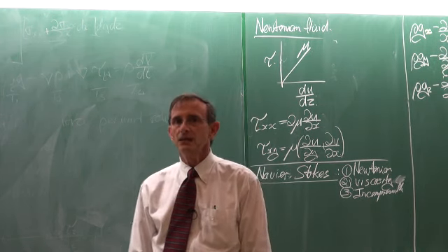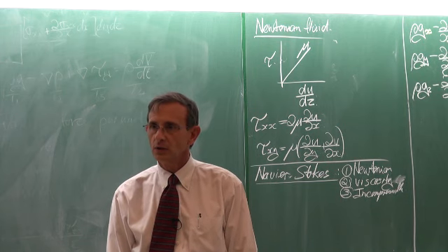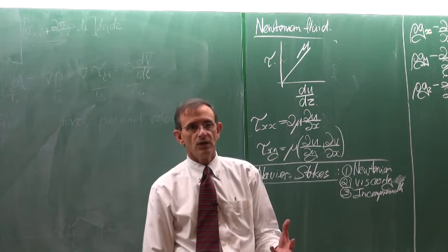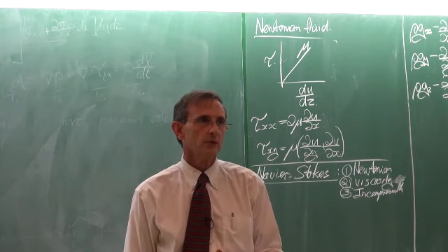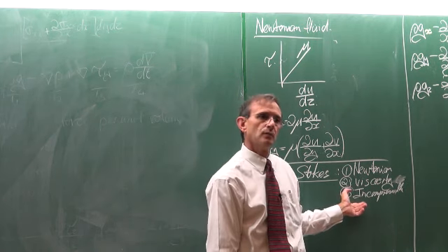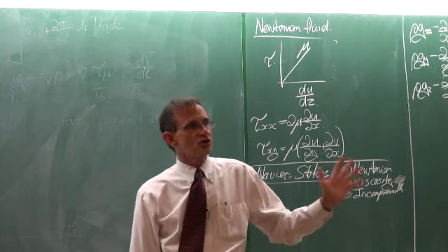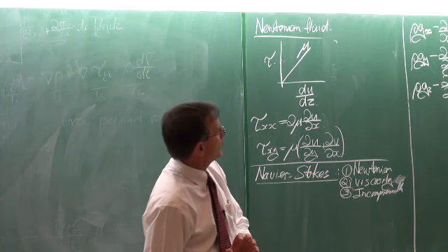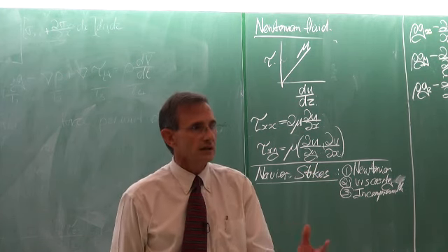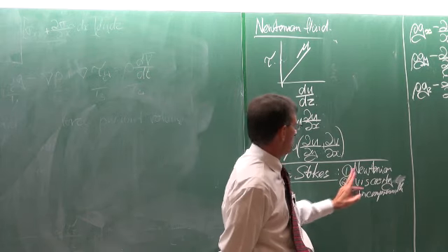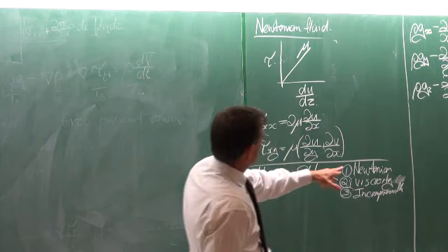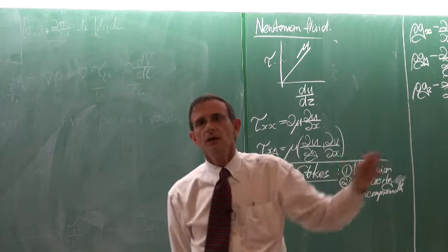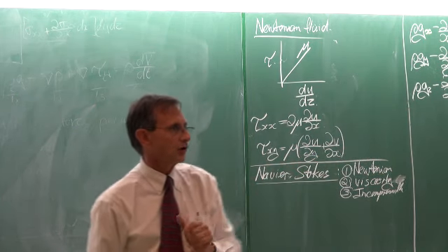Because at a Mach number of 10, flow is not incompressible anymore. Okay, normally at Mach numbers smaller than 0.3, flow is incompressible. Okay, larger than 0.3, compressible flow. Okay, if you consider a flow situation where you want to solve the heat transfer and fluid flow through somebody's heart, then you work with blood. Blood is not a Newtonian fluid, so you have to go back and correct the equations. Obviously, it makes them much more complicated, but then, only then, you'll be able to get a right answer.